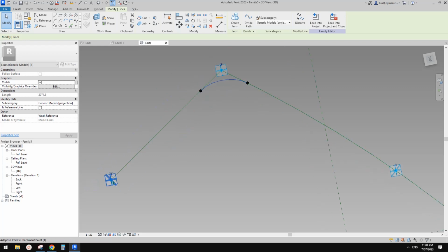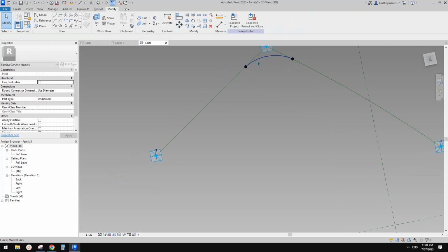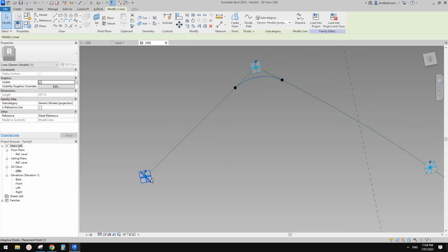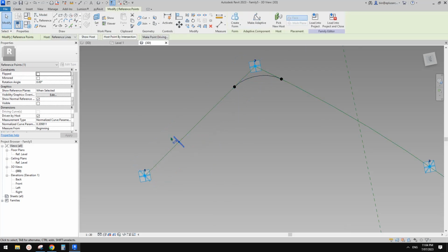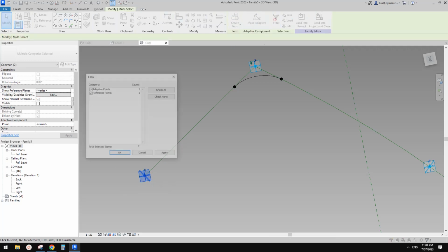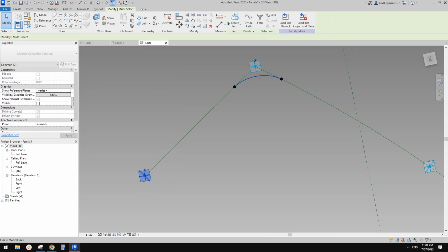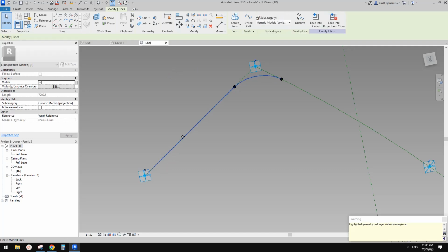And then we just need to connect to here. But if we directly select this curve and connect with this point, it will create this one. So we need another point here close to the point 1. So Control Z, place a point, draw on face, place it on here. Measure from this point, change to segment length, and type in 1. Now select these 2 points, make sure there are 2, and also select this. It will allow you to create almost a straight line to continue this curve. So it is one spline.